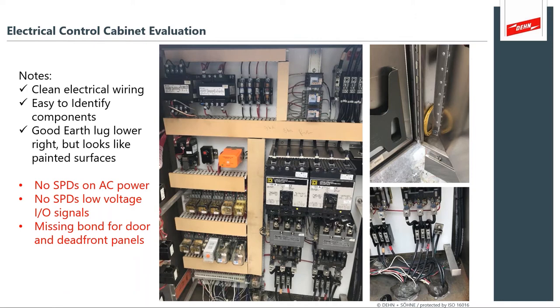And you also have that trouble with equipotential bonding. If it's not bonded and there's a surge, that door essentially sits at a different potential. And now you'll have a voltage, and now you'll have surge currents wanting to flow through the hinge, and you'll get that terrible arky sparky that is a source of ignition, and it's also a source of damage.